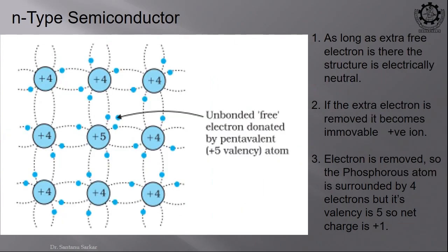So, we all know these basics. Similarly, if the doping is a pentavalent material, for example phosphorus, then the opposite thing will happen. After making the 4 covalent bonds, we will have one extra electron. That will be our free electron. So, for n type material our majority carriers are electrons, right.